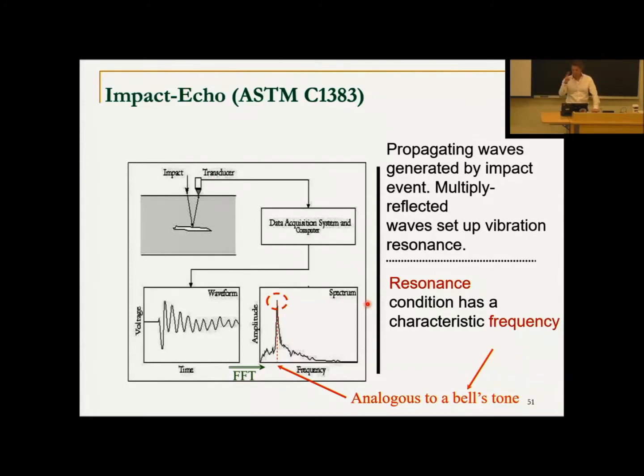It's just a mapping or a translation. We remap this information in terms of a frequency spectrum. So now we have an amplitude of the energy over its frequency content rather than over its time. So these two signals represent the same phenomenon. They're just referring to it in a different language, if you will.